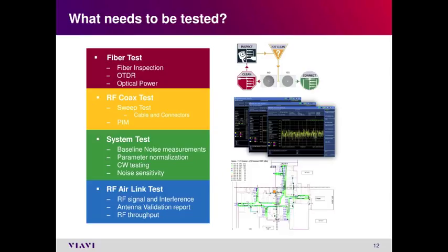You have to make sure that OTDR testing is done, optical powers are right, and all the fibers are clean. So you have to inspect it. If it is clean, good, you connect it. Otherwise, you go and clean it, and then you go back and inspect it again.